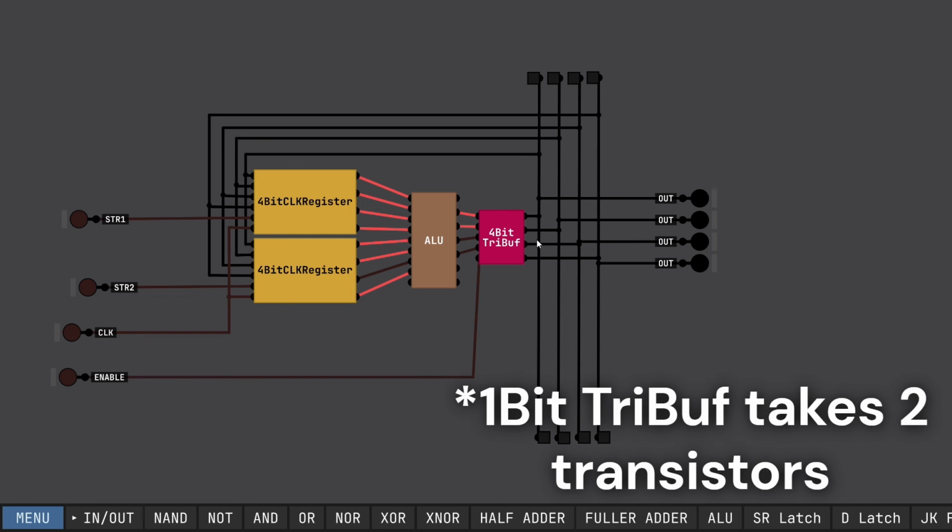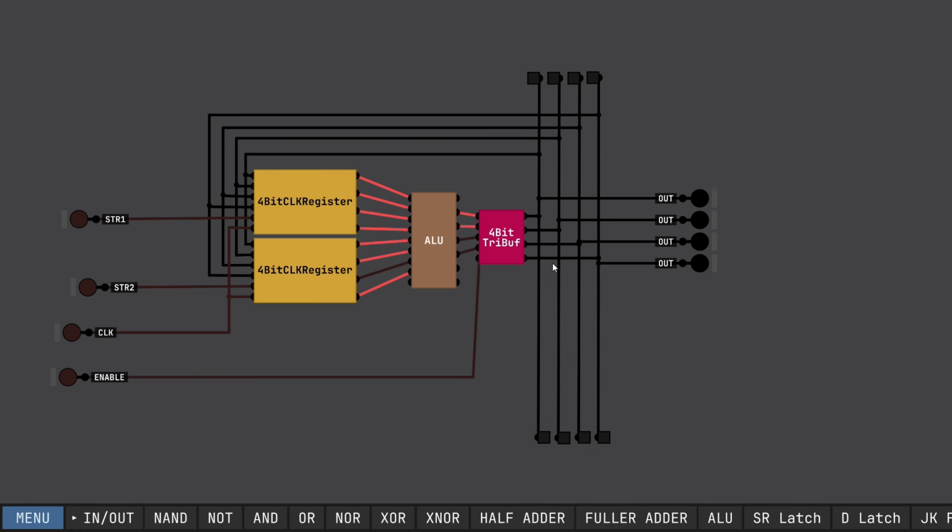There's really actually no point of having a bus for this circuit, but I just want to show how it works really. So what we have is these two registers going into this ALU, and then a little tri-state buffer to go into this data bus. So other components in a computer could output their data onto this bus, and any of these registers could store the data if they wanted to. So we could have multiple units just like this, all outputting data on the same bus. But this is just one of the units.